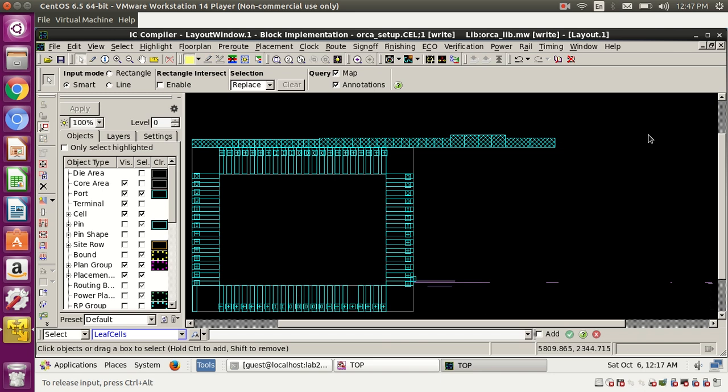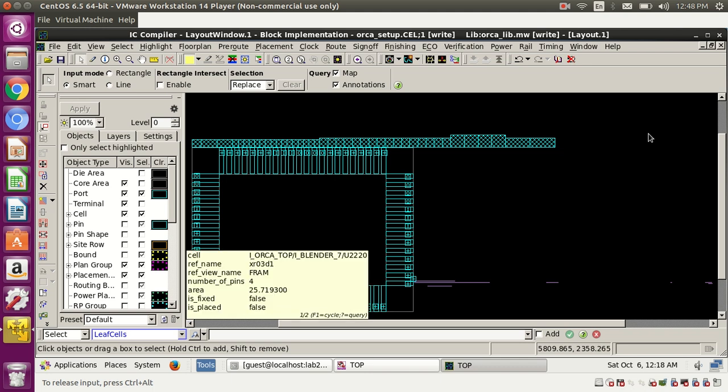Now, different widths. I think in the last two classes I explained these different widths. The point is, we can have M1 at 50 width, but normally we use hardly 0.032 microns, 0.04 microns, or even 0.02, 0.01 microns only, because we have many standard cells, lakhs of standard cells, and the first layer on those standard cells is M1. If the M1 width is larger, then to access the pins, we have standard cell pins.